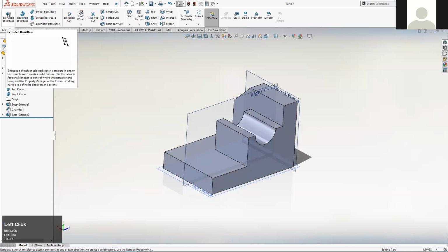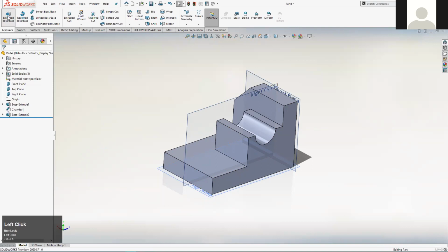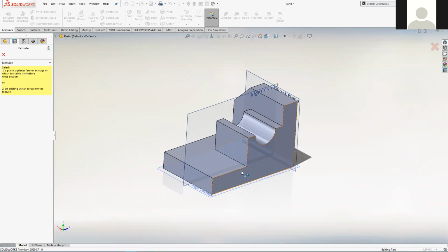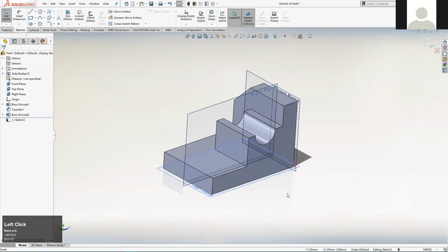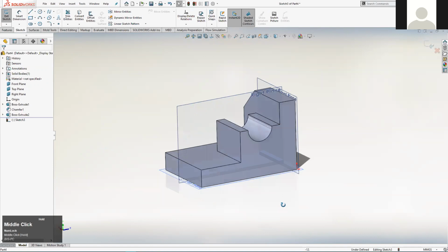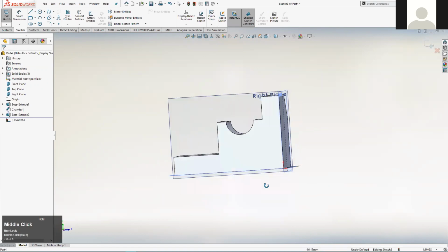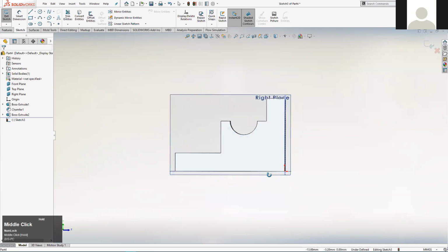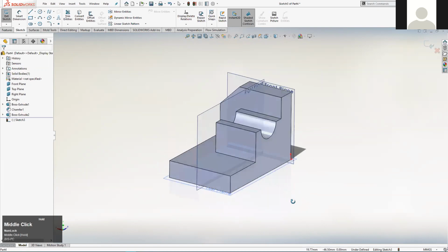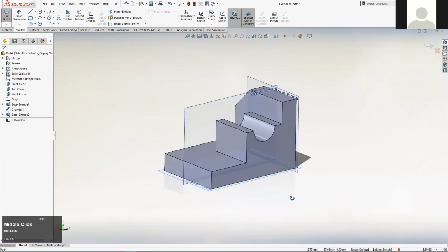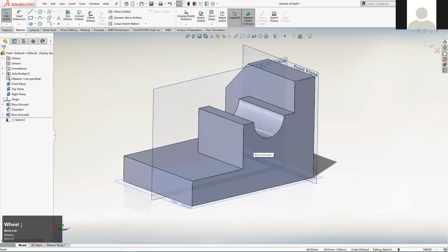So it's going to be an extruded boss base again, and we're going to sketch on what we're calling the back face here again. So we'll select that as our sketching plane. For this particular one, it's such a simple sketch that I'm not going to feel the need to get the system to rotate my view round so I'm normal to it. I'm going to do it from an isometric position, sort of here.